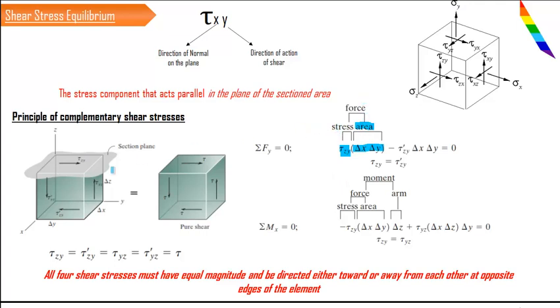Multiplying these together will give you the force value. It's very simple. So if you consider the y direction, you have got two shear stresses, one on the top surface and a second one on the bottom surface, and this bottom surface shear, which I think is not visible, is mentioned as tau dash zy.